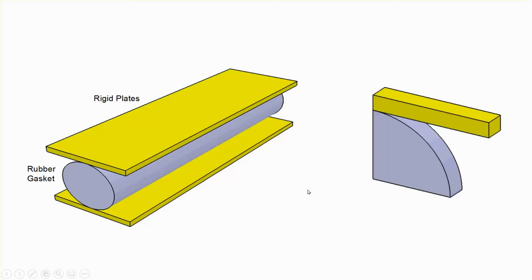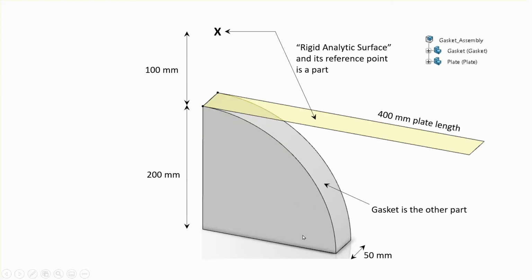And we're not going to be doing it as a plane strain problem because in 3D Experience, the finite element solver, which is really Abaqus, does not have two-dimensional elements, okay? So we're going to be modeling something like that, where the front face, back face, bottom, and left are all planes of symmetry, in other words, the rollers. And the top, we're not going to model with elements, either solid or shell. We're going to be using the analytical rigid surface that's available. So this is the way I'm going to be modeling the problem.